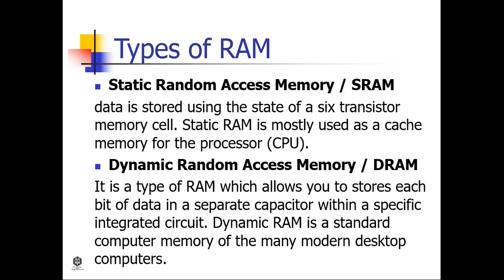Since transistors always leak a small amount, the capacitors will slowly discharge, causing information stored in them to drain. Hence, DRAM has to be refreshed, or given a new electronic charge, every few milliseconds to retain data.